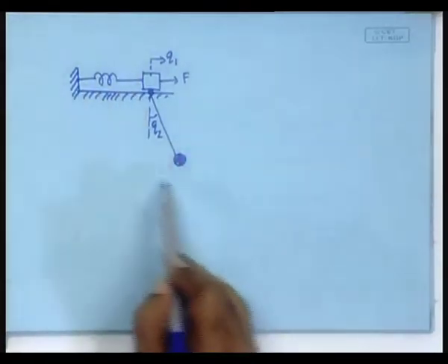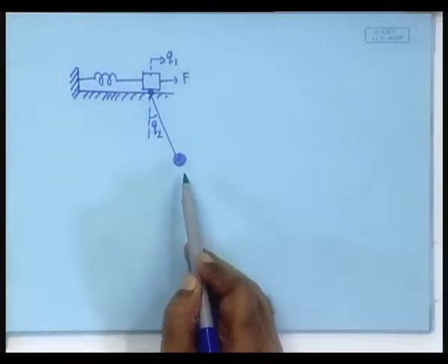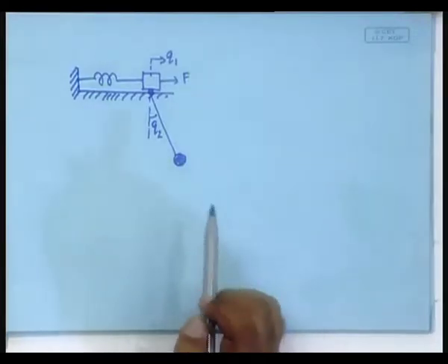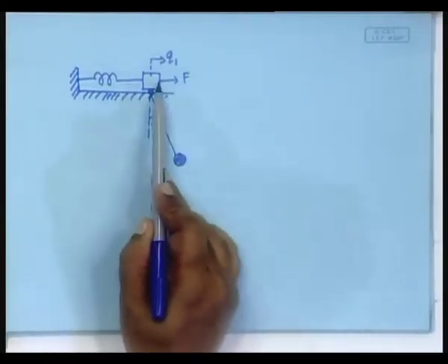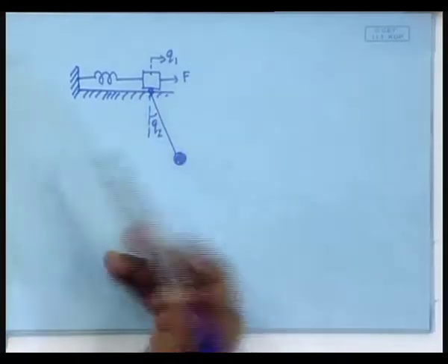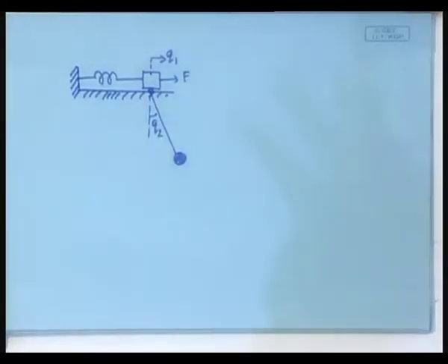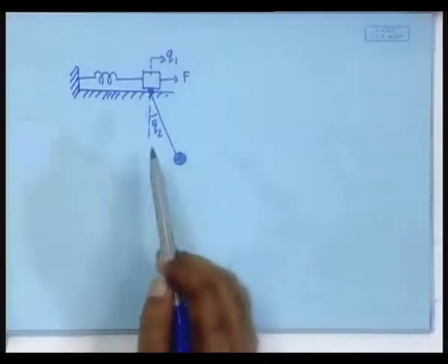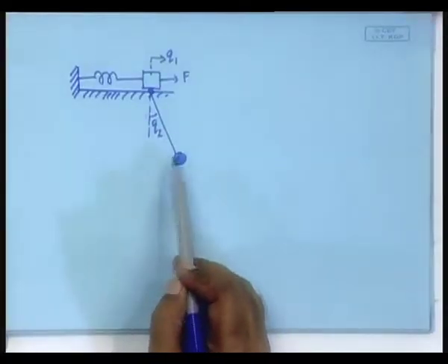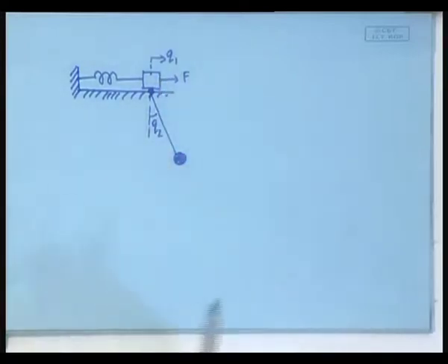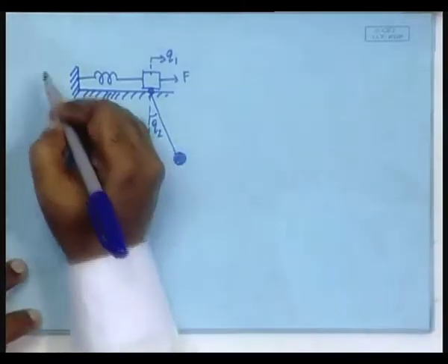Does it uniquely define the positional status of the system? Yes, it does. Notice that one is a translational variable, another is a rotational variable. Generalized coordinate, that is the concept of generalized coordinate. Whatever you want to define as the minimum number of coordinates that defines the positional status of the system, fine. Okay. Now, can you write down now the kinetic energy and the potential energy of this fellow with respect to this q1 and q2? Try this, it will be good. So, this was problem 5.